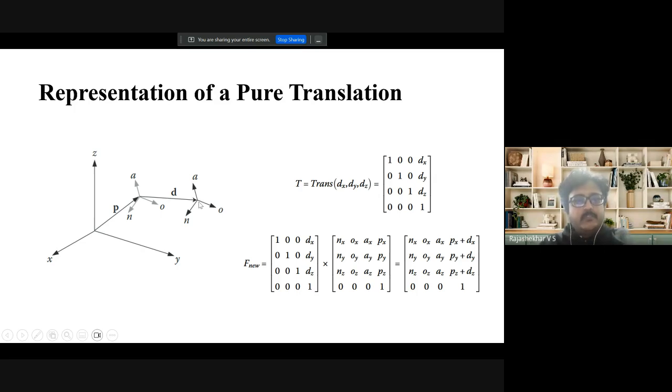But in robotics, when you are doing some complex operations where the rotation of this frame also happens, that is, this matrix will also be taken into consideration. That time, the complexity is taken care of by this entire 4 cross 4 matrix. So that is why this matrix is not disturbed anyhow, and only the translation happens. So this is the translation matrix, and we are able to proceed forward. Okay, is it clear?